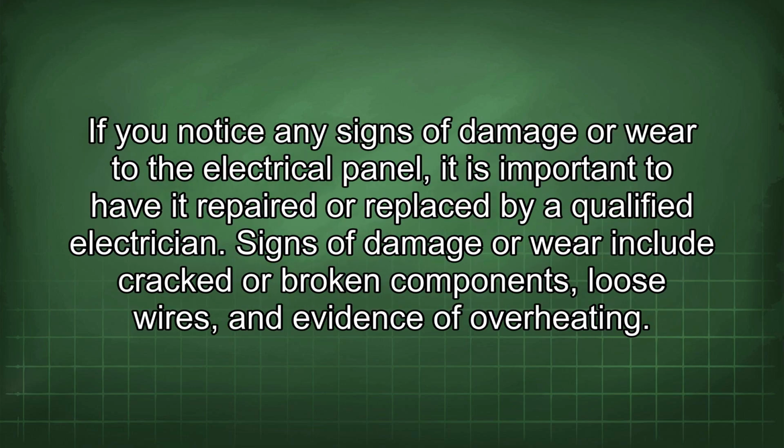If you notice any signs of damage or wear to the electrical panel, it is important to have it repaired or replaced by a qualified electrician. Signs of damage or wear include cracked or broken components, loose wires, and evidence of overheating.